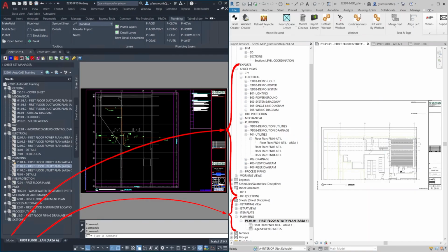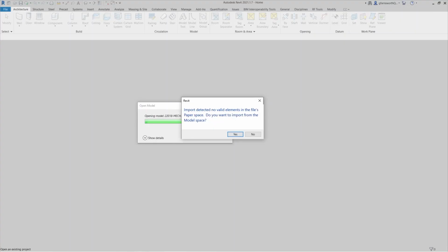Revit and AutoCAD understand that the other has the same types of work areas. If you import an AutoCAD file into Revit, Revit expects that line work will be in model space, and that work should link to a view. So if you drew a diagram in AutoCAD in paper space and then try and import it into Revit, you will see an error. This isn't a terminal error. This is just Revit letting you know that it expects actual drawing work from AutoCAD to come from model space.